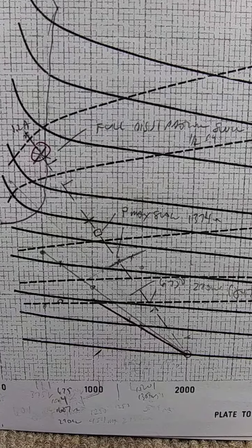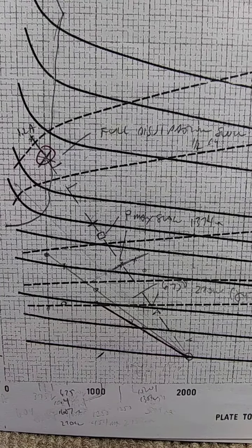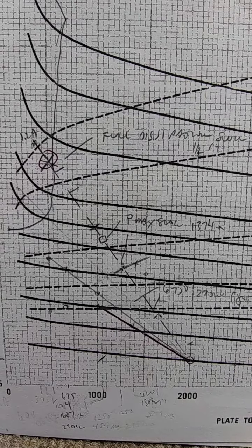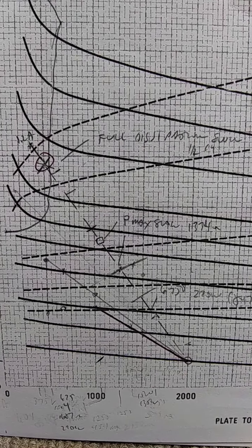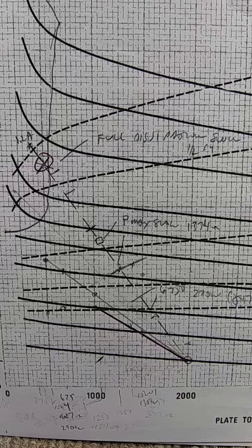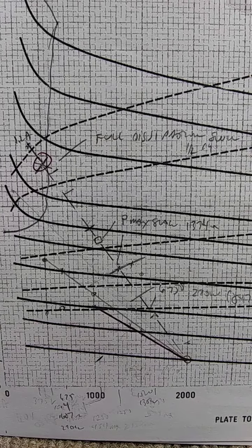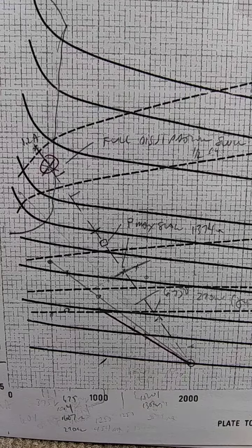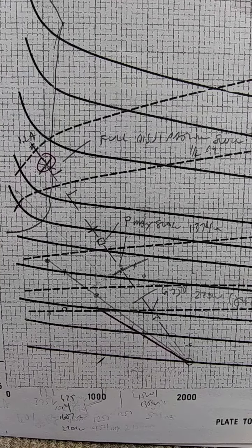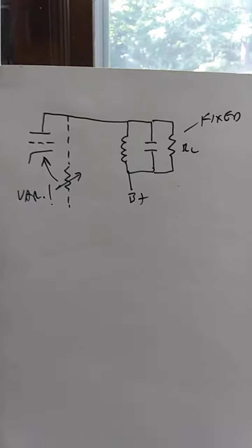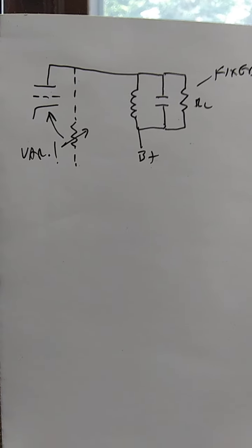There's a super, uber, mega critical observation here that is hiding. Very well hidden. And that observation is that these lines and this circuit will not work for a power amplifier. Now, yes, that circuit will act as a power amplifier, but what I mean is the traditional circuit with the tube with an inductor in the plate, and instead of that output network, a pi or T or some kind of matching network across the tube.